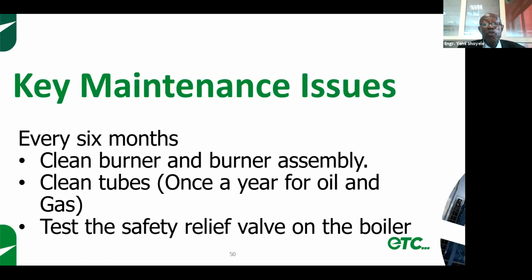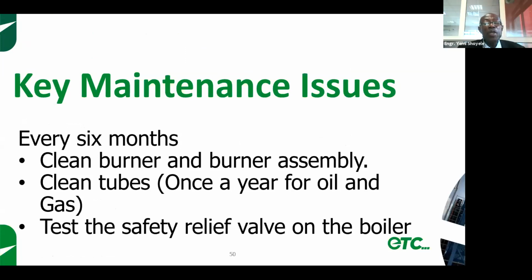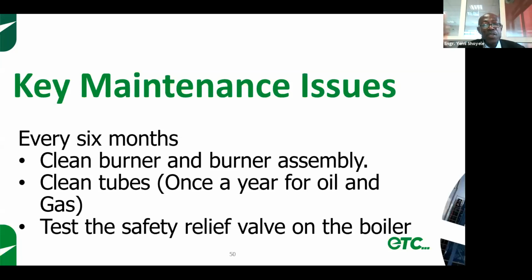For the fire tube boilers, because you have your water outside, inside the shell, you must do a chemical cleaning of the boiler once a year. Same as the water tube boilers. You must also do the chemical cleaning of the inside of the tubes once a year, so that you do not have a problem with heat transfer.